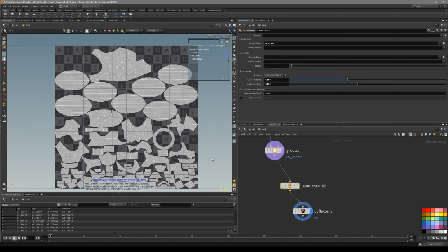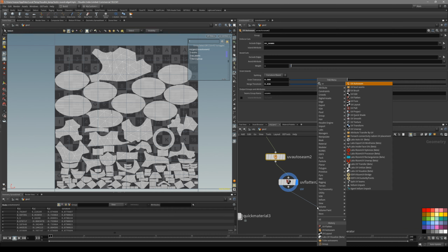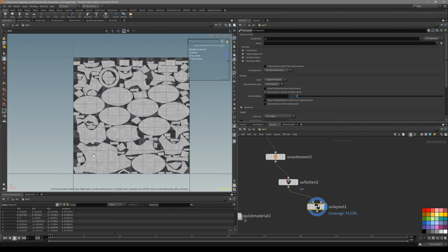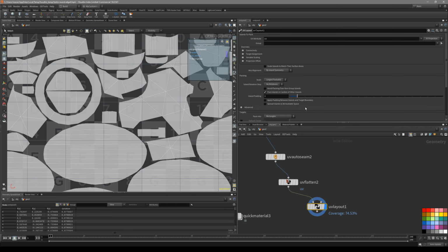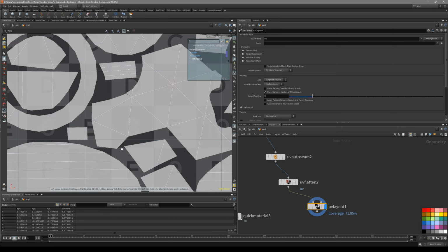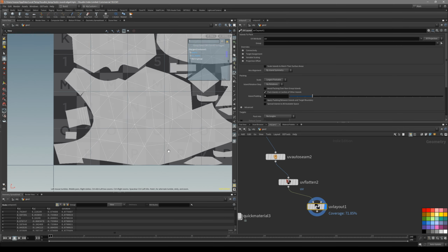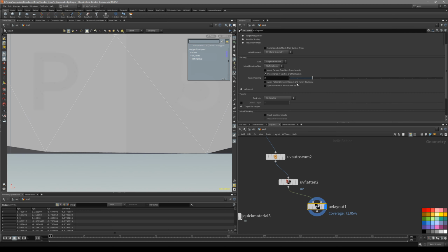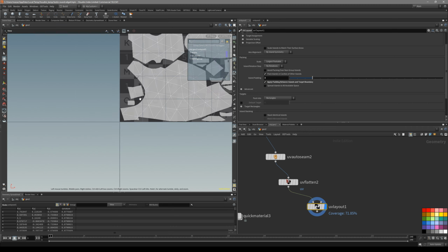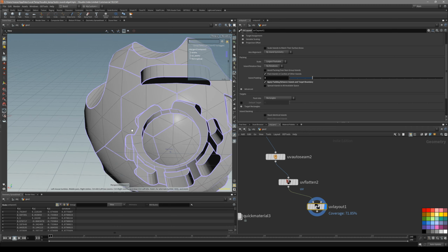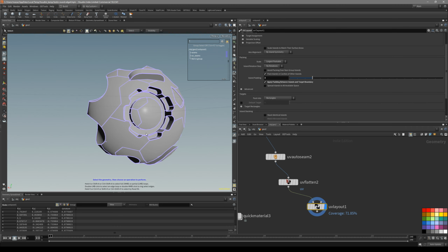And for us to maximize our UV space, remember to add a UV layout node, like that. This is going to basically pack our UVs to maximize size, and for the normal baking, make sure you show island packing padding, maybe something like 3, so you don't get any bleeding. And let's also apply it between the target boundaries, like that. So now we have enough space for our normal baking, like that. So basically this is our UVs.